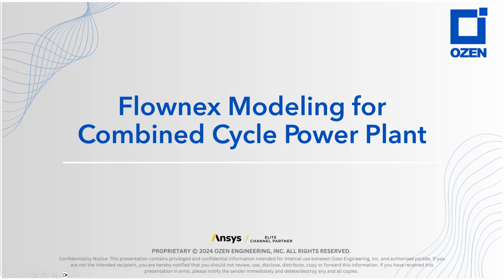This is a schematic of a power plant with combined cycle, and by combined cycle I mean that we have the gas turbine for power generation, and we have another turbine, which is a steam turbine, that basically uses the heat from the exhaust hot gases from the gas turbine and uses it for producing steam.